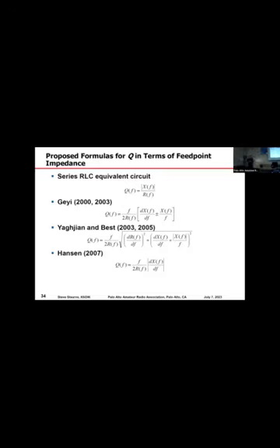But you cannot actually measure the Q of the antenna on any measurement you make at the feed point or any other feed point. You can slide the feed point around. It still doesn't help. You have to go to the fields and integrate the power in the fields to get the Q, to get the real Q. Otherwise, you're fooling yourself. Okay, next slide.